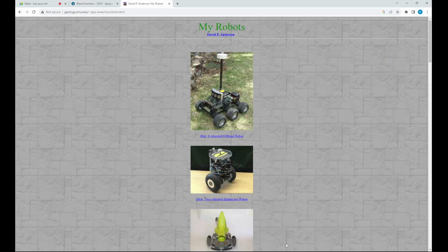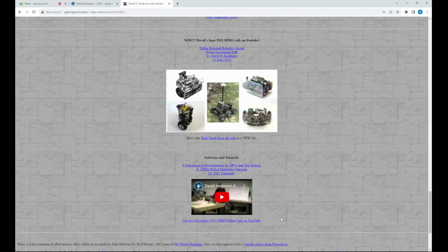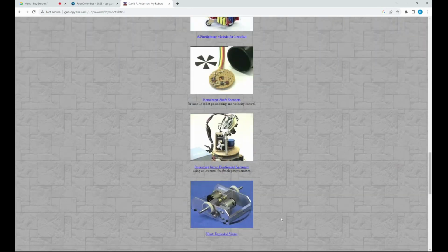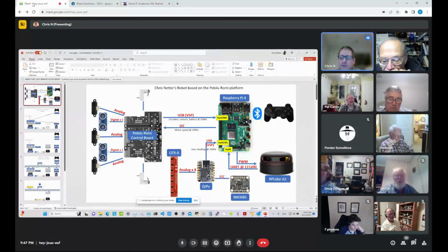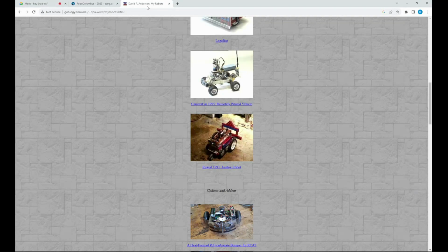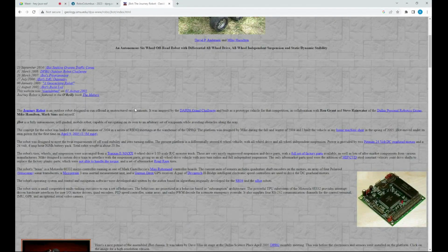So you're just reading your X and Y on your accelerometer? Again, I don't recall if I'm using an Adafruit library or some other library, probably Adafruit, for talking to the BNO085, which is an Adafruit board that I have here. I'm reading that at 100 hertz and spitting out the data at 100 hertz. Okay, so it's a fairly fast update.